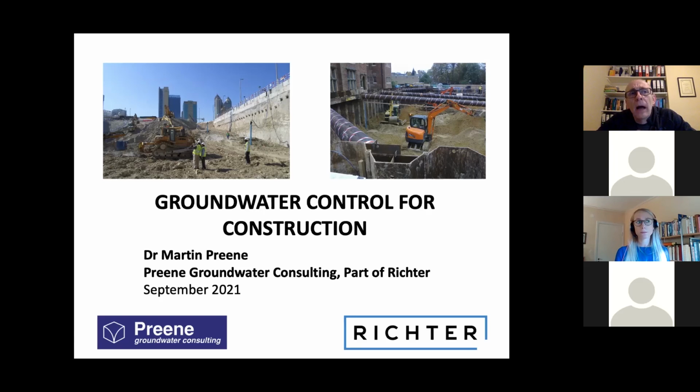And my interpretation is the well point method is around about 100 years old, and it's been developed really not theoretically, it's been developed by experience. And I think if you find a design where you're outside that range of maybe 1 metre to 3 metres, and you think your design is saying you need to have a different range, then I think it's the wrong method. That's one of the indicators that you're looking at a problem where you need to look at a different method. Like a very wide spacing of well points means the flow rate might be very low, and so maybe you can sump pump it. And a very close set of well points means maybe the flow rate's very high, maybe for deep wells or something similar. So that's not a great answer, because I don't think there is a simple answer to that. But the vast majority of well point systems are in this range, probably 1 metre to 3 metres.